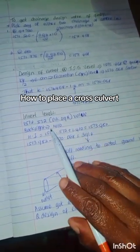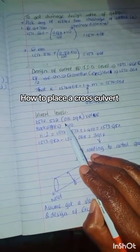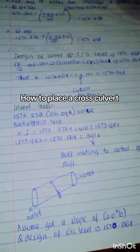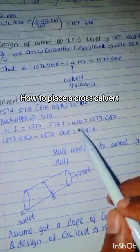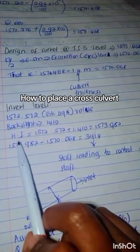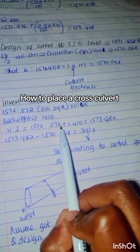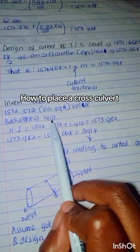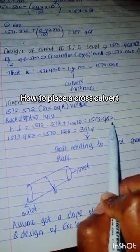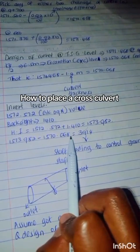Another thing you need to know is the invert levels. For example, here I'm going to use the value of 1.14. You get the height of instrument, to calculate the height of collimation, that is 1572.572 plus backsight 1.40, and you get 1573.982. So this height of collimation, you minus 1570.068.